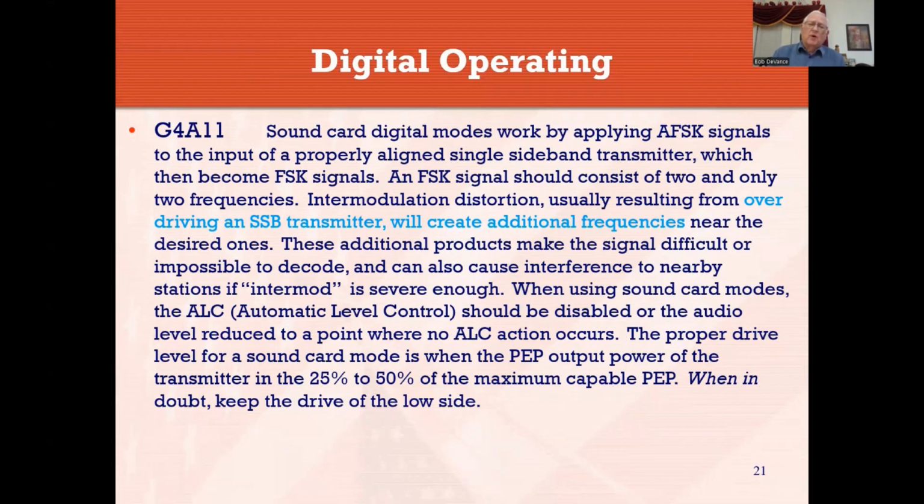When using the sound card mode, we need to watch the ALC, the automatic level control. Most all of our newer transceivers have a meter, and one of the choices to display on the meter is ALC. Automatic level control is the transmitter trying to optimize the power out of the transceiver. In the digital modes, we're pushing it pretty hard anyway, so we want to cut our power back on the radio far enough that the ALC doesn't kick in and try to control it.